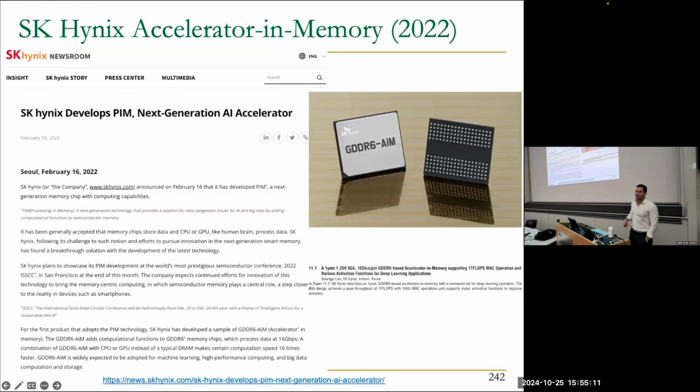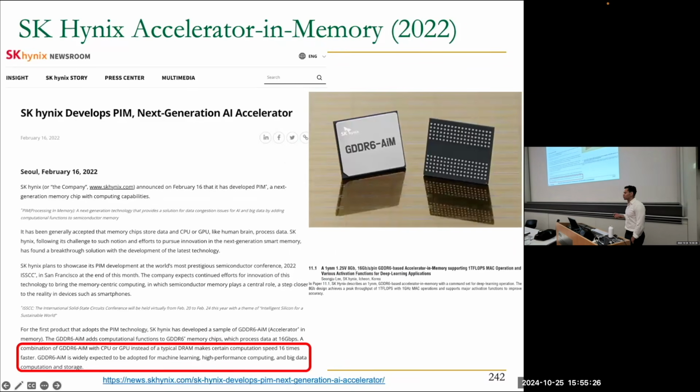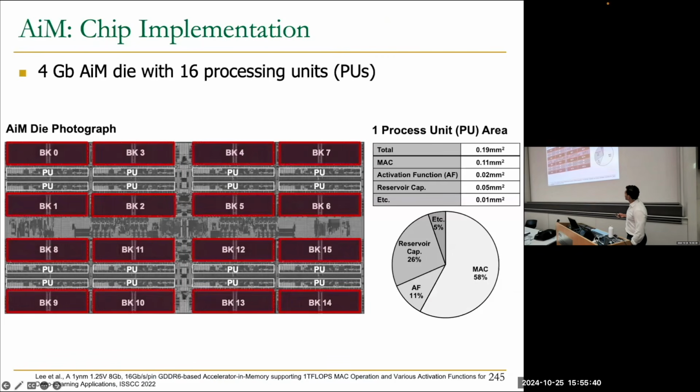So another memory manufacturer, SK Hynix, also has its own PIM chip now. It's called AiM, and they also have a follow-up called AiMX. They keep adding X on stuff. Here, again, this is targeting neural network inference. And what changes is that they are using a different type of memory, GDDR6 memories. Those are usually high bandwidth memories utilized, for example, in GPUs. So this is the design of the chip. It's a little bit similar to the design that I just mentioned from the Samsung work.